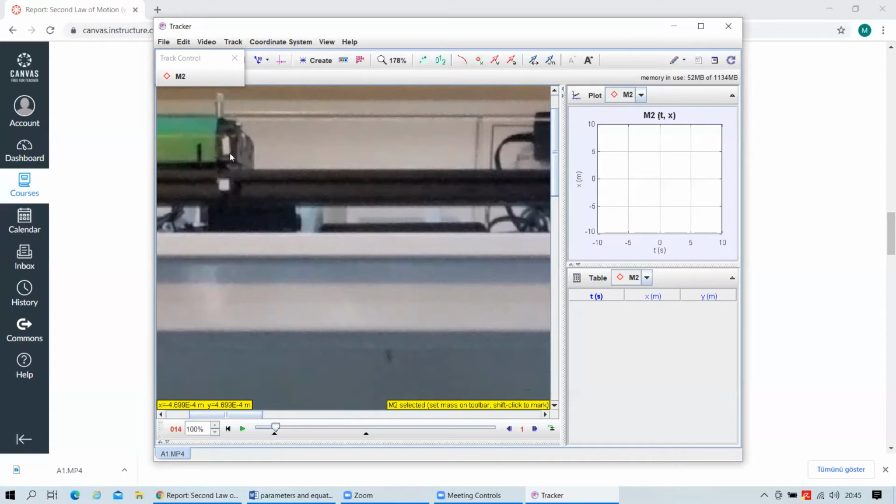And for this, I'm pressing the Shift button together with the Control button. Now I'm holding both the Shift and the Control button, and you see there appears a circle sign. Now the mouse pointer turned out to be a circle. Just bring it over this corner that I take as the reference point for taking X measurements for the card and press the left mouse button.